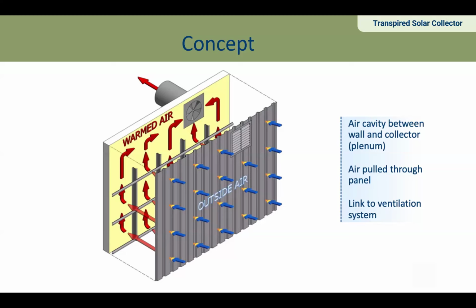So typically, when you have a metal wall panel installed on a building, the airspace behind it's back there for draining and back venting. But that air temperature behind the metal panel will typically be 50 degrees warmer than the outside air temperature. So I'm here in Ohio today and it's about 50 degrees. And if I was in a metal building, that means the airspace between the insulation and vapor barrier and the metal cladding is going to be somewhere around 100 degrees, which is quite warm.